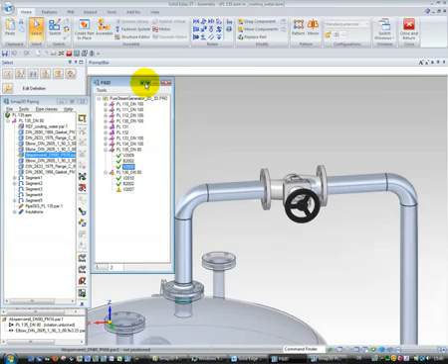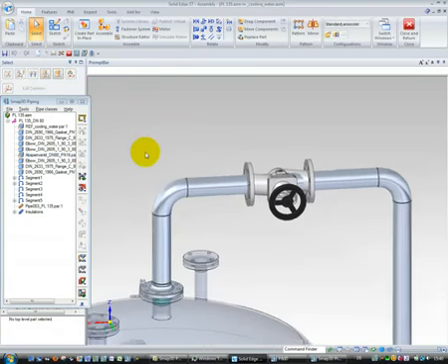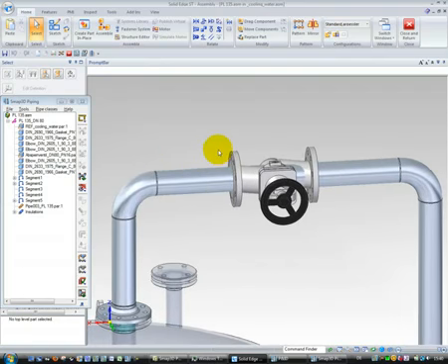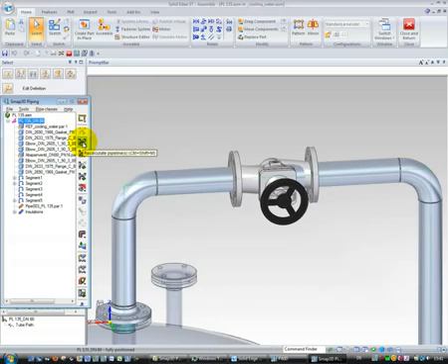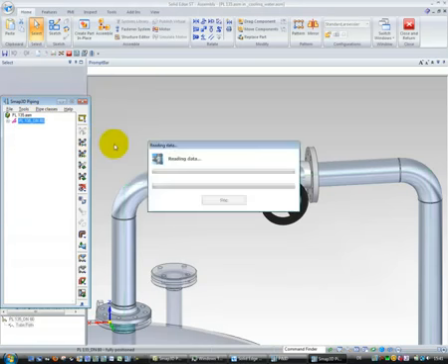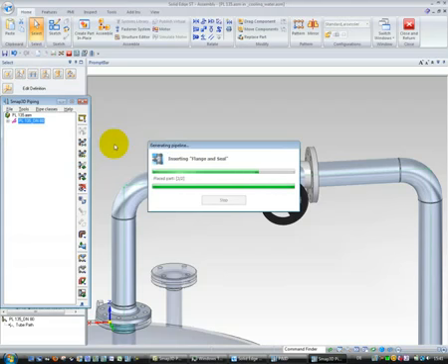But in addition to that, in 3D we can recognize that, for example, some information or components are missing, like the flanges at the connection of this valve. This is controlled and driven from the pipe spec, and for the update we just have to demand the function called Recalculate Pipeline, and with this my automations and plausibility checks run again.